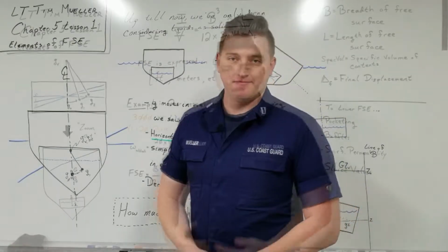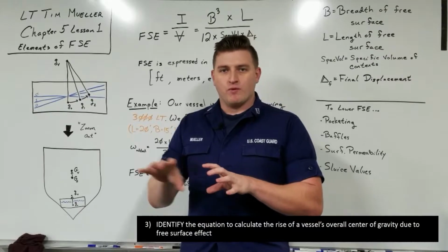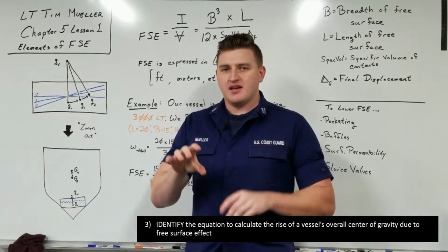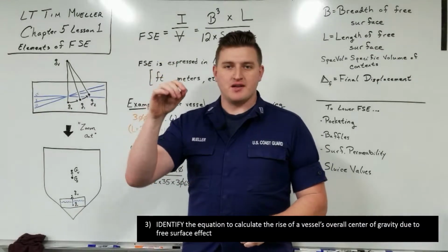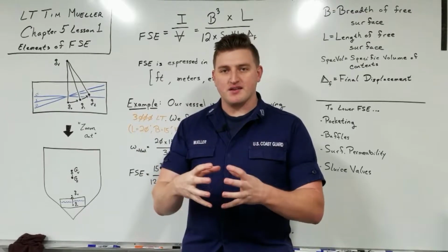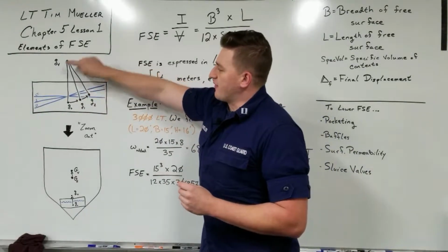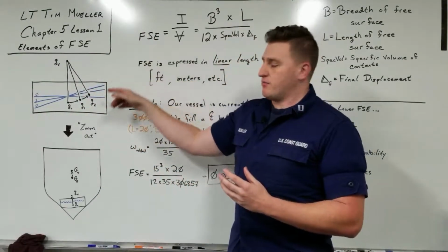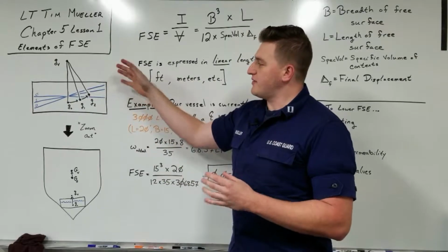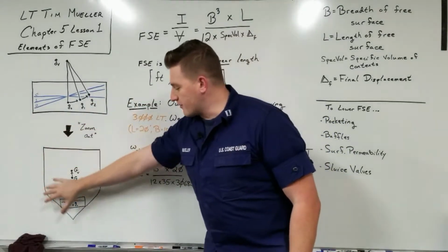All right, so we've already taken a look at how that little g with the changing in inclination can be modeled as a virtual rise in that little g, the little g being the center of gravity of the contents of a tank. Now, we've seen it goes in an arc and it goes up to this virtual point in the middle of that swinging arc. Now, let's zoom out for a second and see exactly what happens to the ship overall.